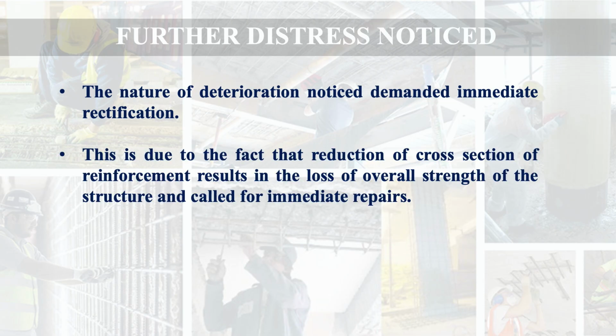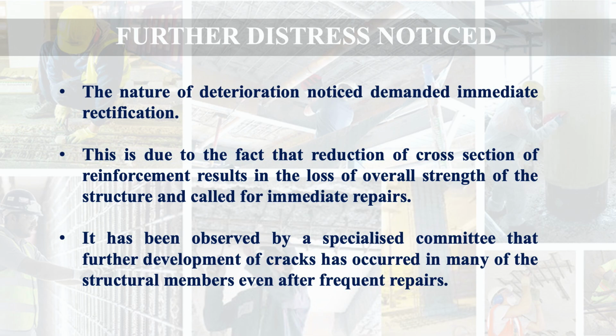This is due to the fact that reduction of cross-section of reinforcement results in the loss of overall strength of the structure and calls for immediate repairs. It was observed by a specialized committee that further development of cracks occurred in many of the structural members even after frequent repairs.